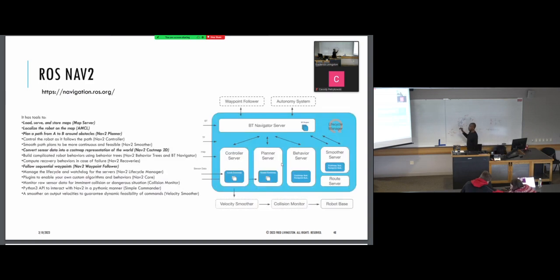This is the NAV2 website here, and this is behavior trees. We're going to talk about that later. But the transfer functions, here's that map that we created, and this is the sensor data. Again, this needs odometry and this needs laser scan, and it could do all this on its own. You're just going to adjust parameters like the size of this to make it run better or smoother, or your filtering algorithm. You're just turning knobs to get a better, faster track time.